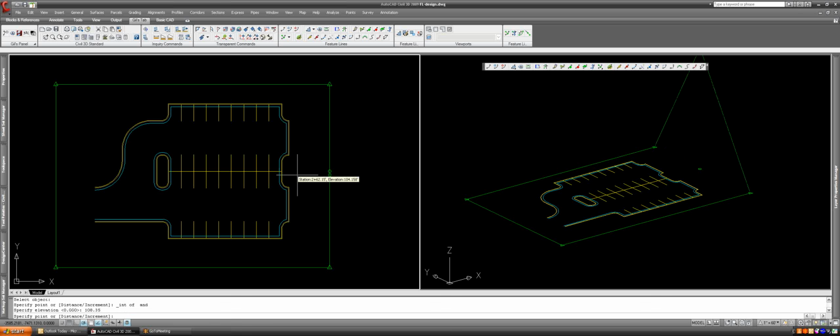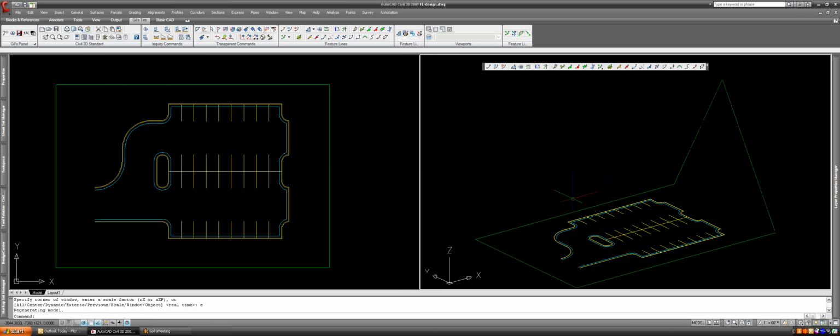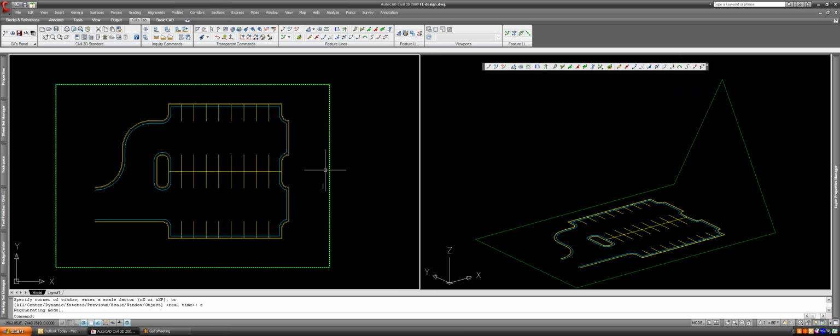Now if you've noticed, once I've hit enter, on the right side of the screen you should see that feature line point straight up like a pyramid. I'm going to zoom extents so that you can see that this point went up to 108.35, which is going to be our low point. Now what we need to do is bring this point up equal to 2% sloping up this way. So from the center line here up, we're going to go 2%.